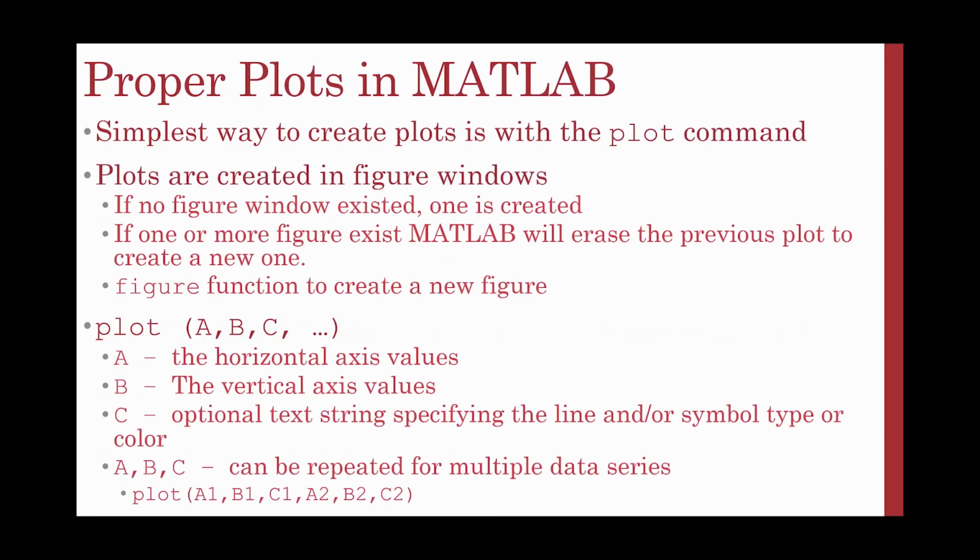So proper plots in MATLAB. The simplest way to create a plot in MATLAB is with the plot command. Plots are created in figure windows. If no figure window exists, one is created. If one or more figures exist in MATLAB, it will erase the previous plot to create a new one. This is an important point. There is going to be a command to have that not happen that we will learn later. The figure function creates a new figure.